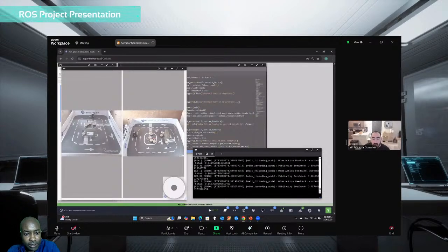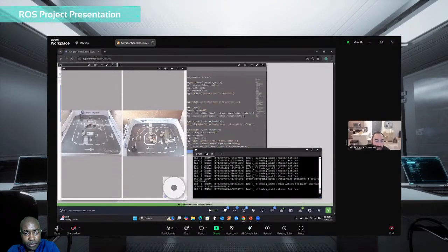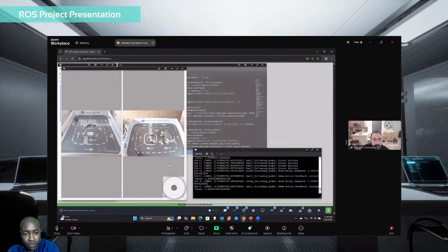What I do is I take the magnitude of any type of error. Let me define that real quick before I get ahead of myself. I have a distance error, which is the difference between the 0.3 meters that I want to be at versus where the right laser is reading. And then I also have an angular index error, which is calculated based off of the index of the nearest laser reading and the defined index of the right of the robot. So in this particular case, this is a 180.